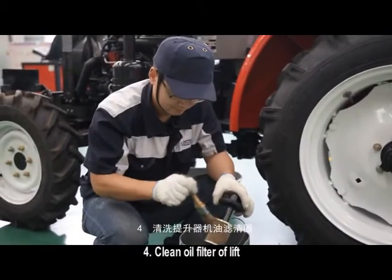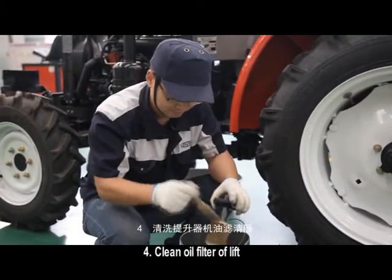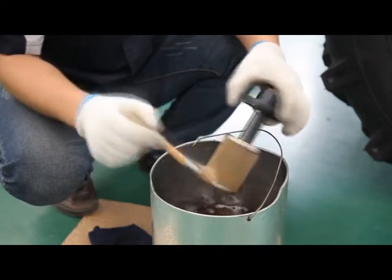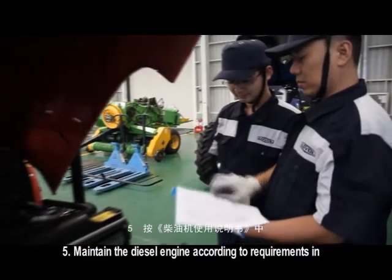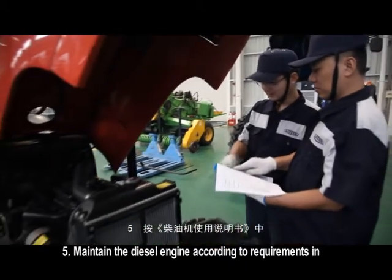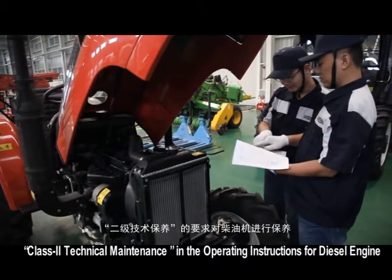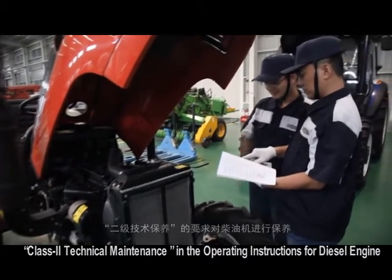4. Clean the oil filter on the left. Replace the filter cartridge as necessary. 5. Maintain the diesel engine according to requirements in Class II technical maintenance in the operating instructions for the diesel engine.